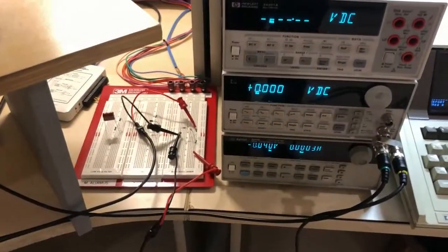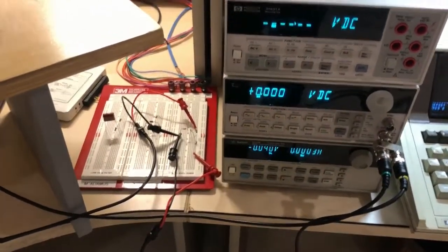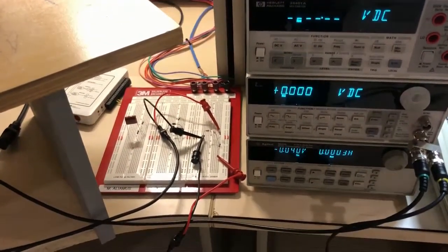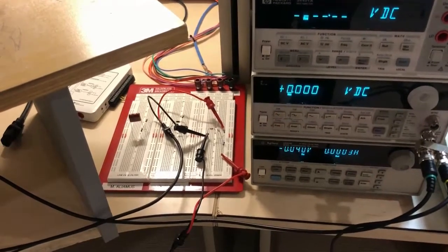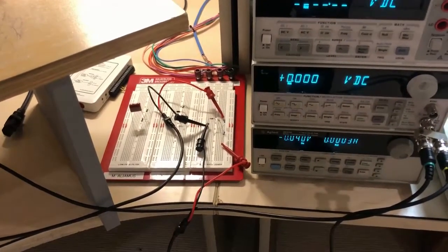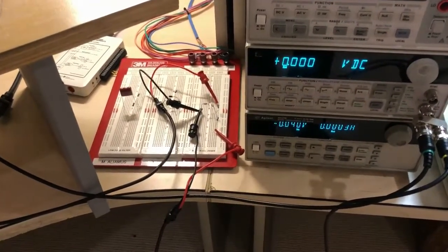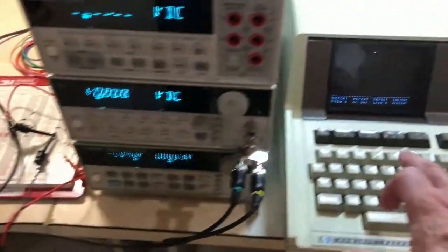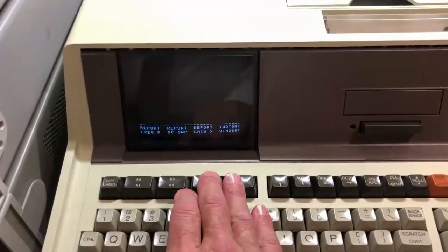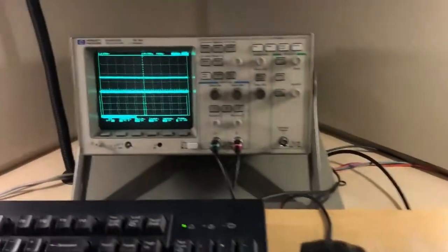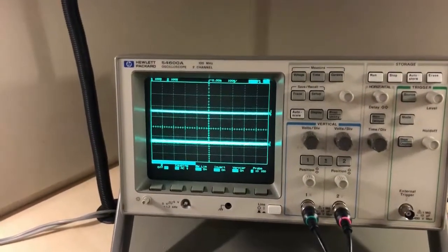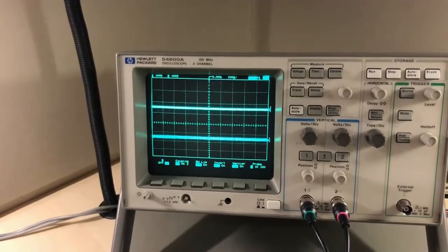We will use a known circuit impairment to demonstrate the gain transfer function, using back-to-back Zener diodes as described in the final report to simulate a heavily clipping circuit. Selecting the gain transfer function soft key sets up the oscilloscope for a 2-channel measurement, the input on the top trace and the output on the bottom trace.